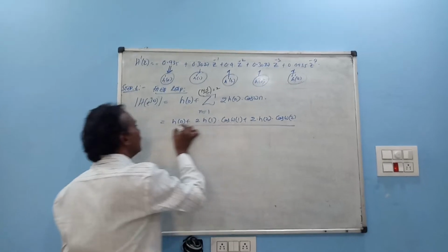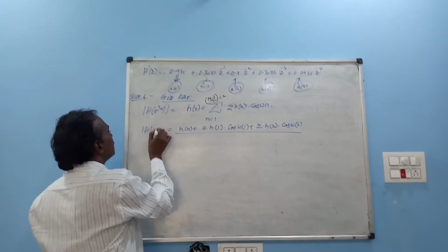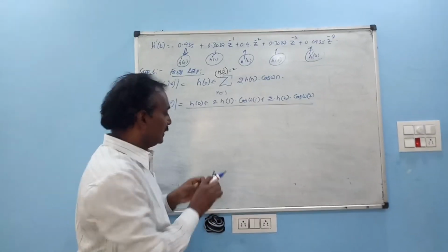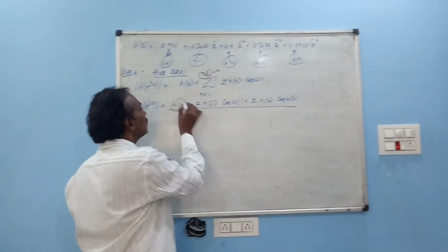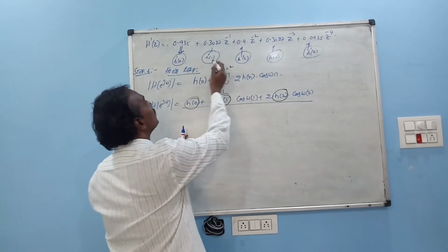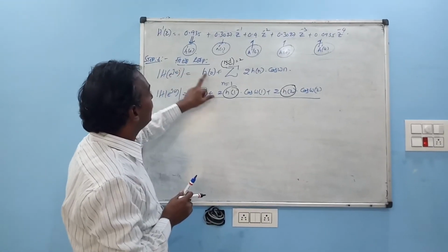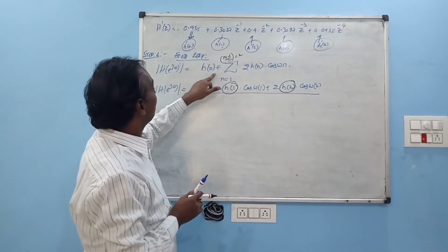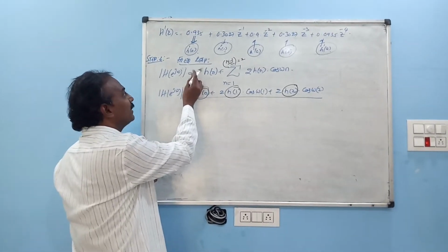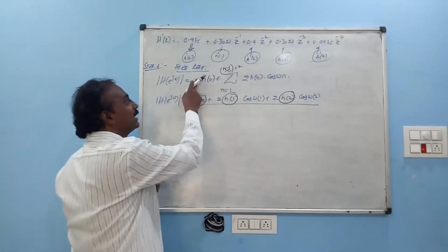Now one important point to be noted. In the modulus of H of e power j omega, whatever values you are writing, these values h of 0, h of 1, h of 2, don't consider the new values, because in the frequency response I am taking the originals only. If I want to shift, I have to multiply by z power minus, here I have multiplied by z power minus 2 terms.